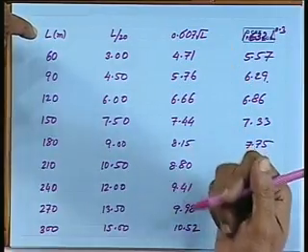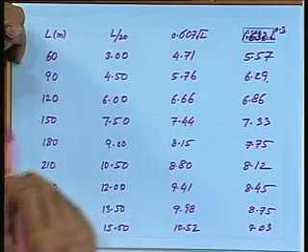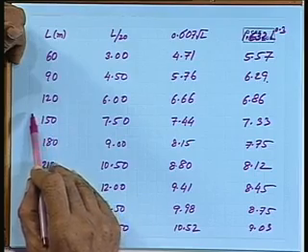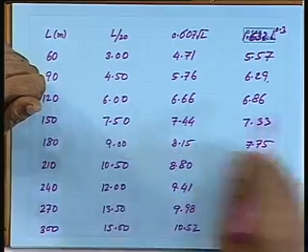But one thing can be seen here, that L by 20 gives you a lower value of the wave height up to a ship length of say 120 or 130 meters. This was in vogue till about 1970-78, when the ship sizes were of that size. And then after the closure of the Suez Canal, when the ship size certainly became larger, this became useless. And they had to go for this 1.1 root L, or equivalent in metric is 0.607. And you can see that at around 120 to 130 meters, all of them will give a similar wave height.